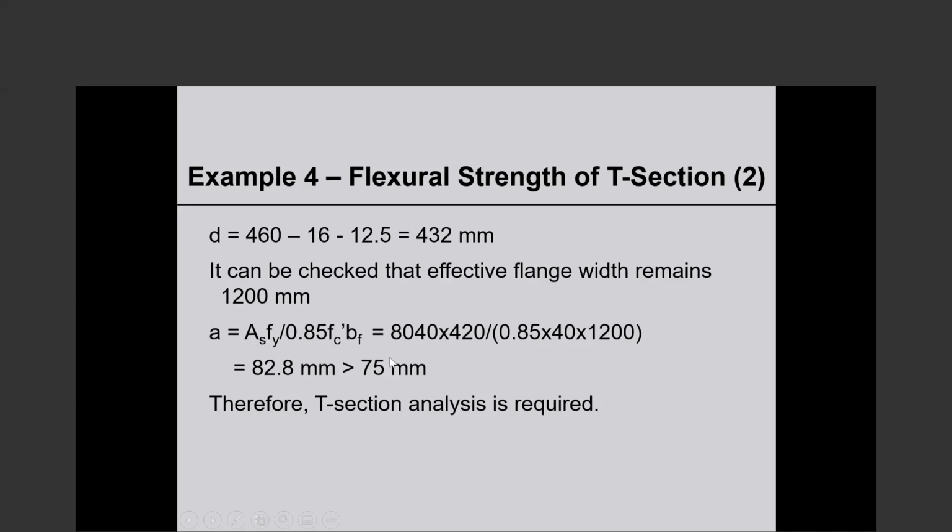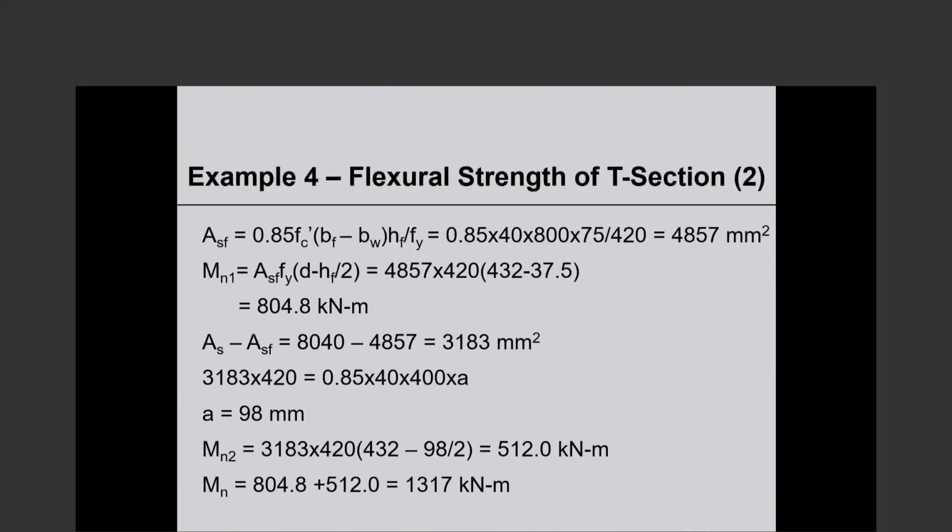That is larger than 75 millimeters. So this confirms, as we suspected, that the stress block depth is larger than the flange thickness.